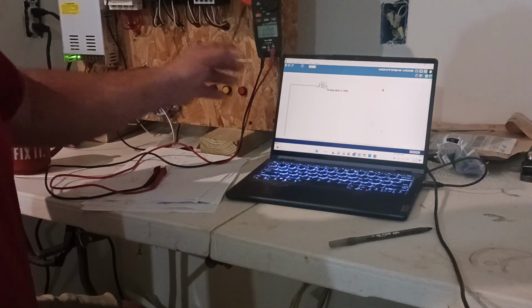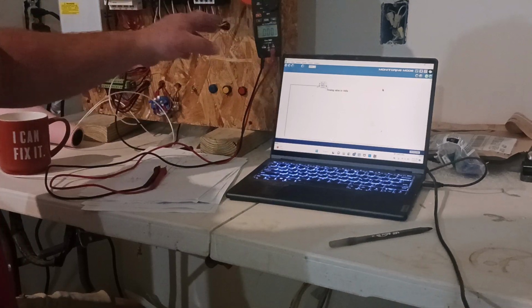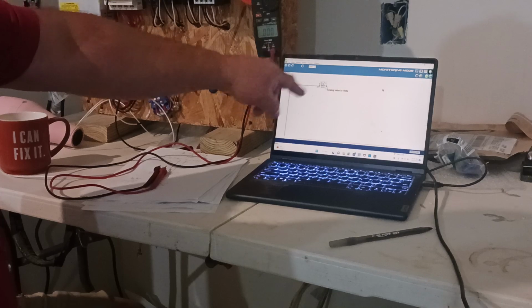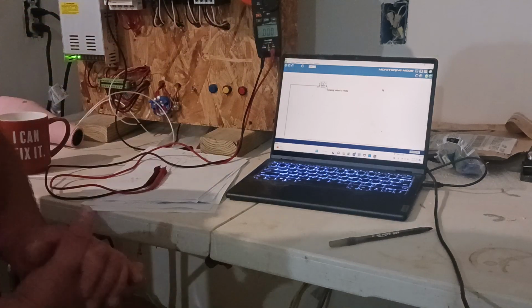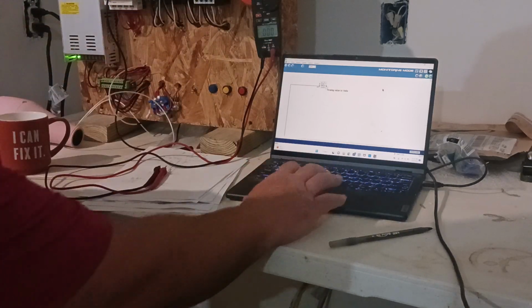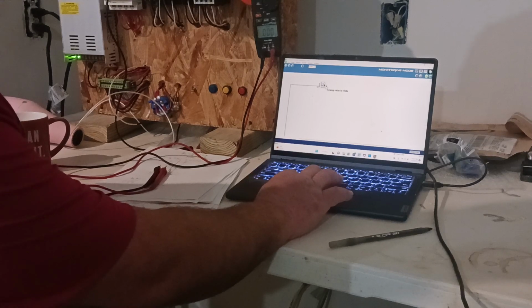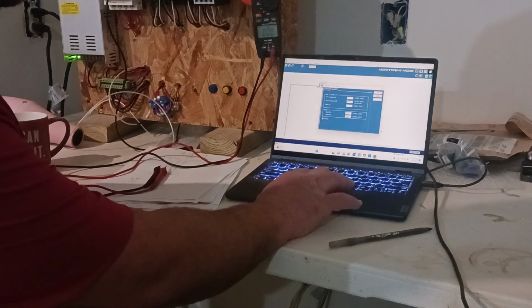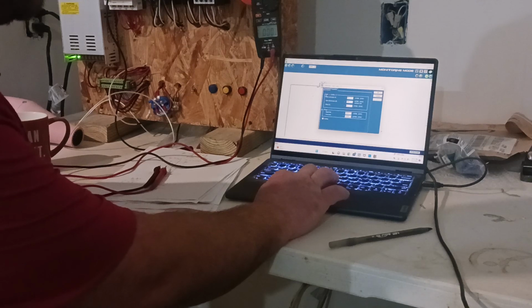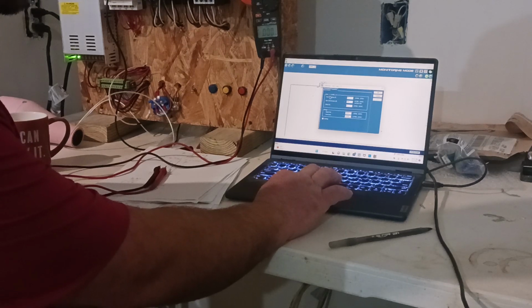So when I apply volts, every volt adds 25.5, and it just ramps up. To get meaningful information, we have to scale it to volts. The easiest way I know to do it is with a linear equation.